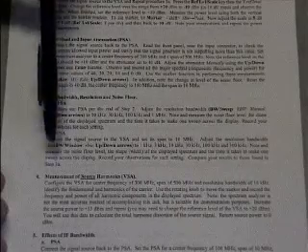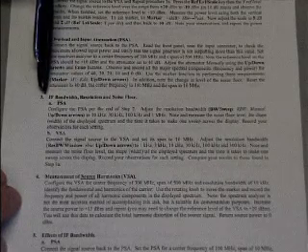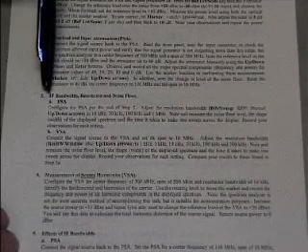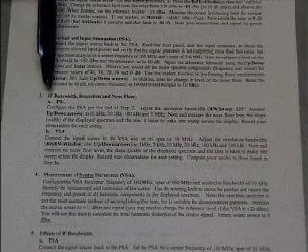Step 3 allows you to look at what happens in terms of resolution bandwidth when you don't have the res bandwidth set properly, or shows you that one spectrum analyzer is going to be good for measurements that the other one can't do.